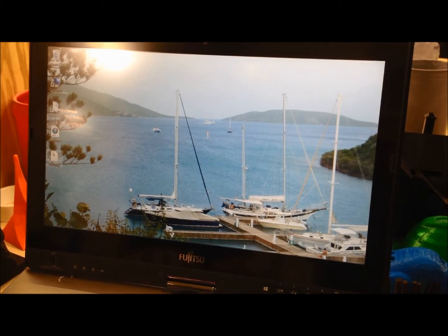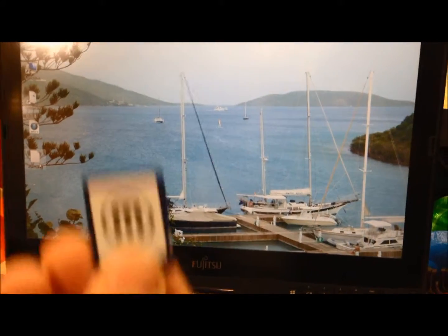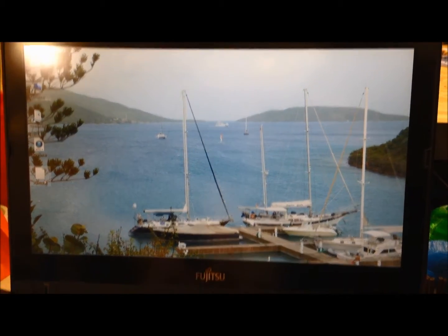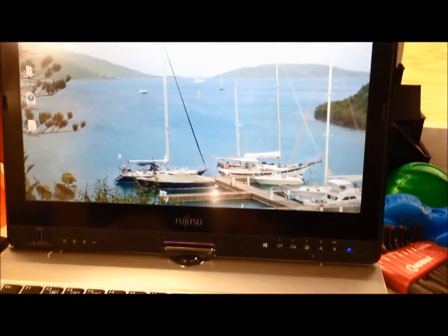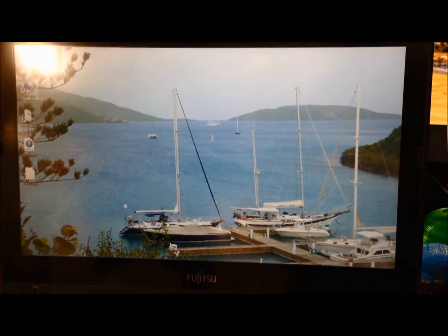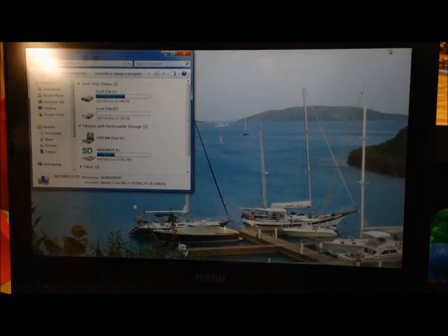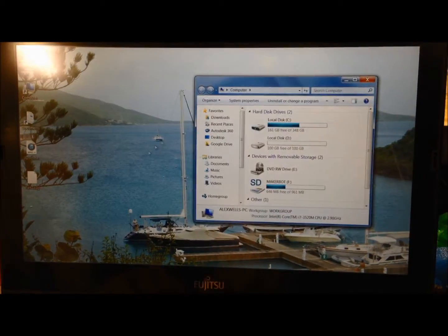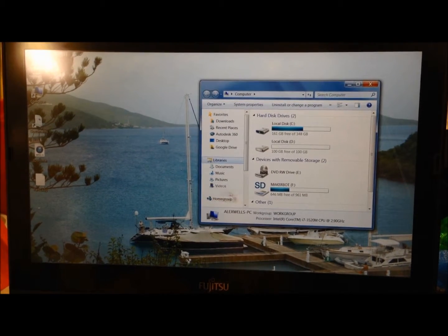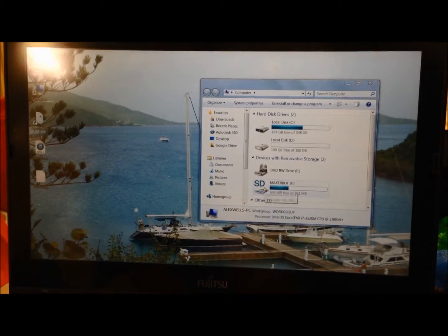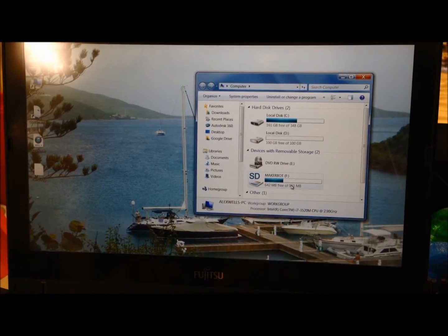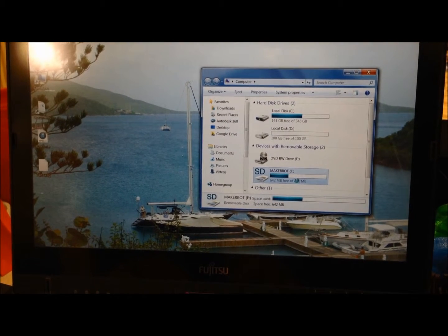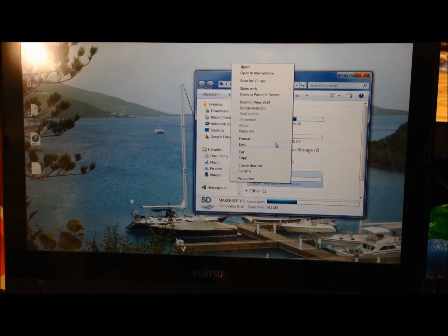To physically print the object, you first must put it on an SD card. This can be done by getting the SD card found in the lab and putting it into a slot in your computer where an SD card can go. Depending on the computer, the location of the slot could vary. Once the SD card is placed in the computer, simply drag your file to the SD card and you're now ready to print it. Just eject the card and place it into the machine to prepare to print the file.